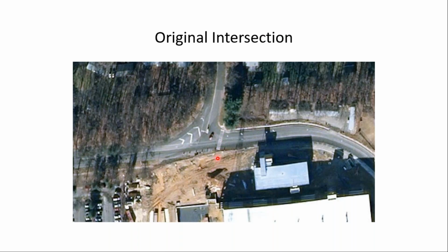skewed, as we call it. It's not at right angles to the roadway, and that's an issue because the shortest, quickest path across a roadway, of course, would be at right angles. That's the shortest distance. When you have a skewed crossing, it means the crossing distance is longer, and it may affect a pedestrian's ability to check for or judge oncoming vehicles or speeds of those vehicles.